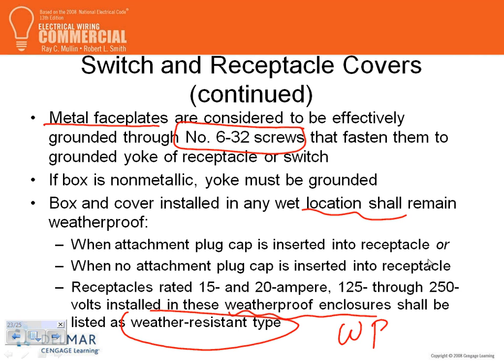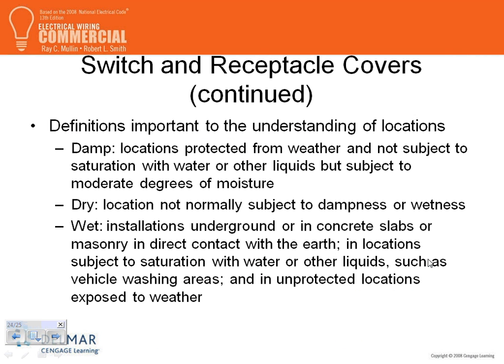So all these receptacles, guys, have to be weatherproof if you put them in a wet location. So for our building, the receptacles outside in wet locations, make sure that you tag them or somehow identify them in your spec or somewhere else as weatherproof receptacles.